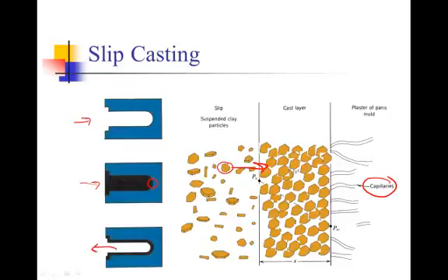The mold can be split apart very gingerly, and then you get the green body, which can be fired to make it stronger. However, this method results in a lot of residual porosity in the material compared to other methods, and usually after slip casting, this porosity cannot be entirely eliminated by firing, and it has to be filled in with some other material.